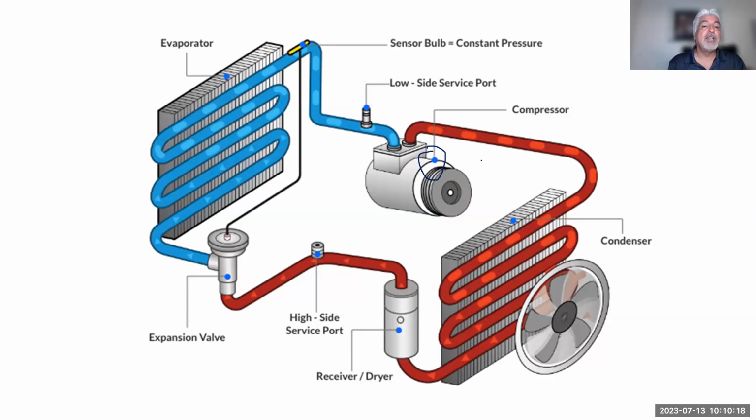So do me a favor. If that compressor is replaced, you need to find a way to get some probes or leads in there and do a voltage drop test across the compressor. So if it's 14.2 at the battery, guess what you should have ideally at the compressor? You should have around 14.2 as well. Some of us are of the opinion that if I'm doing a compressor, I'm going to replace the AC compressor clutch relay, because that relay's contacts could also be compromised with excessive resistance and cause a voltage drop there, in turn restricting the amperage going to the clutch itself.